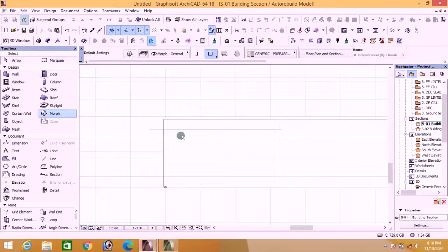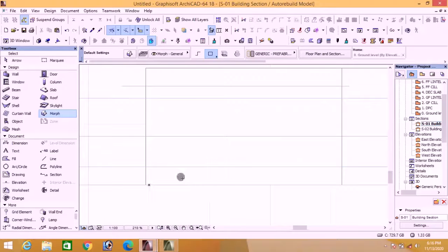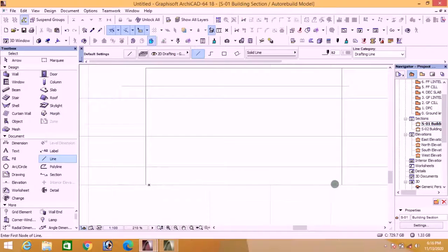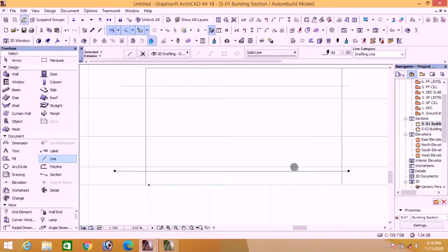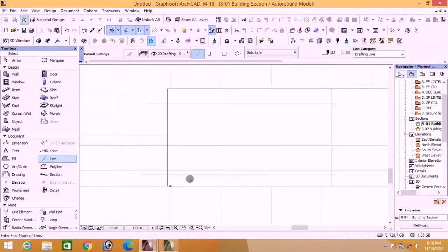And we want to draw a beam that will cut down this way in a stylish way. First, let us put the thickness of the slab that will be at this position. Use your line and measure it 450. Can you see that? Then get the middle. Copy. Use a line and get the middle. Alright, let's change the color of this line to be simply black.